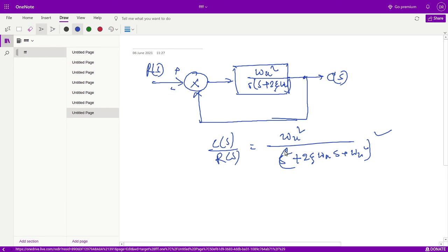That's why two poles exist, because in the denominator the maximum power of s is 2. Now we apply the input as the unit step function, equal to 1 for t greater than 0, a causal function, not an anti-causal system. After some mathematical computations, we will get the form.